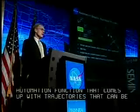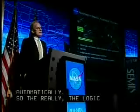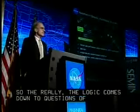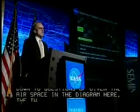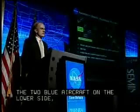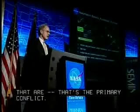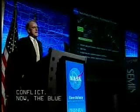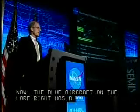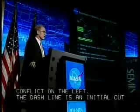So really the logic comes down to questions of, given the airspace in the diagram here, the 2 blue aircraft on the lower side are the ones in the primary conflict. Now the blue aircraft on the lower right also has a secondary conflict with the green aircraft coming in from the left. The dashed line is an initial cut at a resolution trajectory, but you can see that resolution trajectory creates another conflict with the orange aircraft coming up from the top.